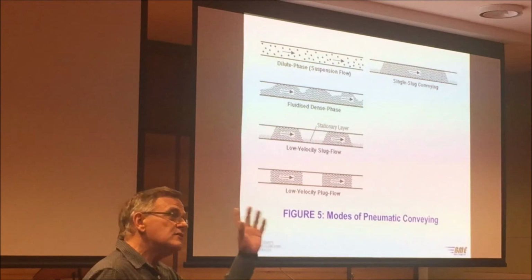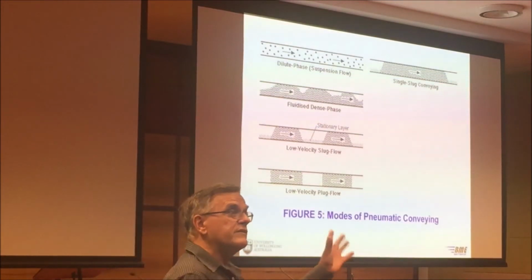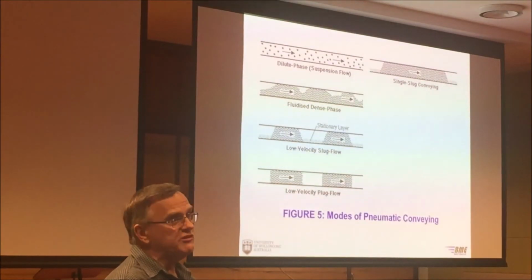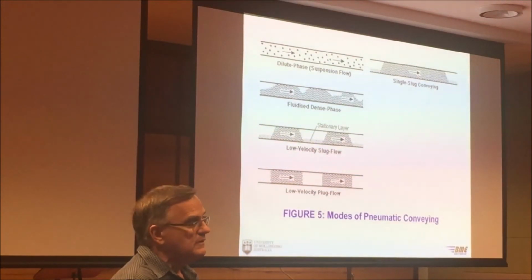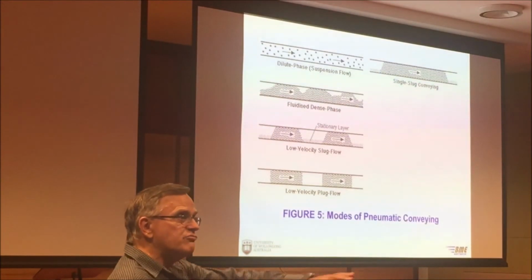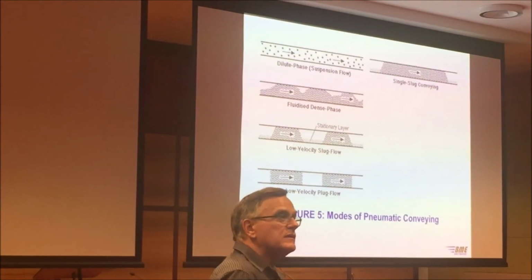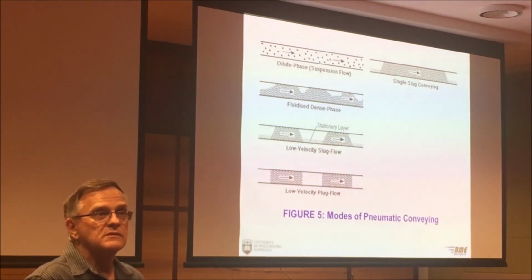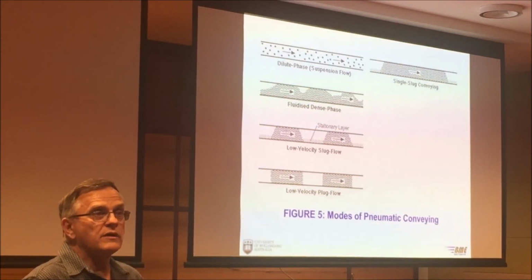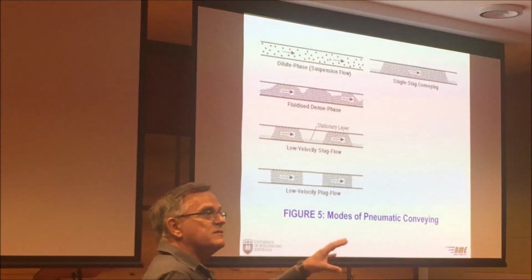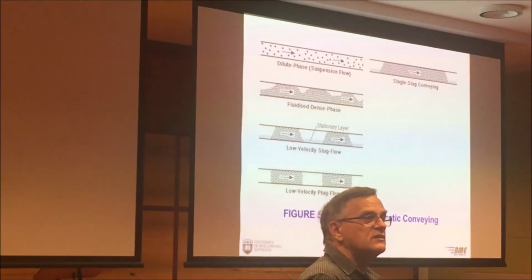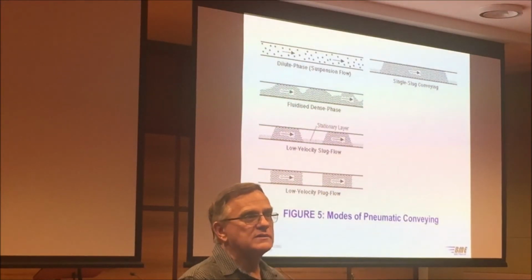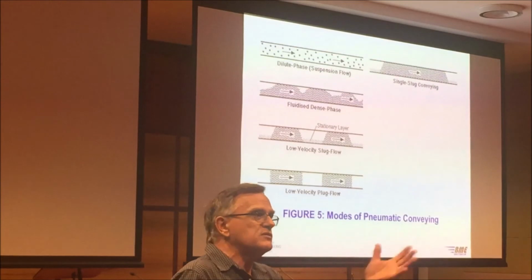And the reason they picked pneumatic conveying for that project? Prior to that was all belt conveying. But the only reason they wanted pneumatic conveying was security. Right? Because in the plant they had belts running with diamonds on them. And they didn't want to subject their workers to the temptation of stealing diamonds. This is true. So they wanted to put everything through a pipeline, so they didn't want to subject our workers to stress of being tempted to stealing diamonds. And that's why they picked pneumatic conveying, and also because it's easy to automate.